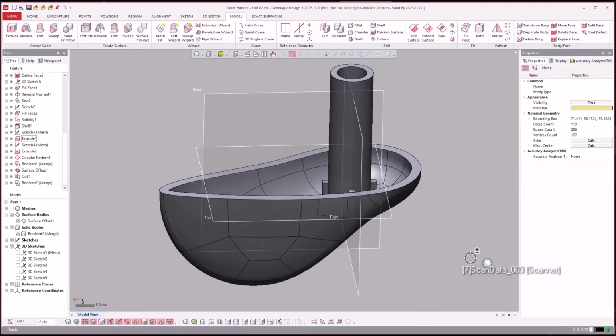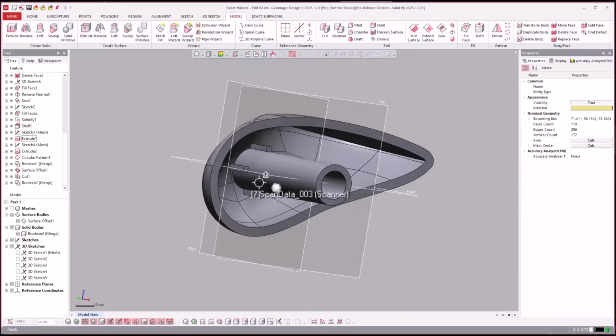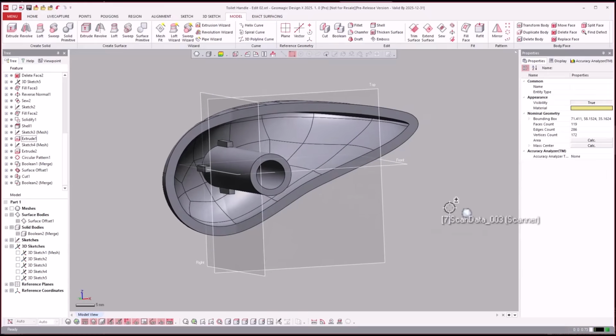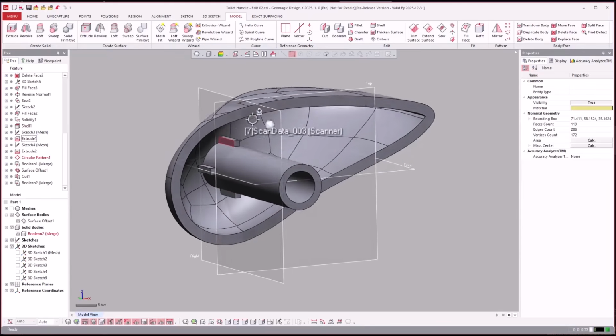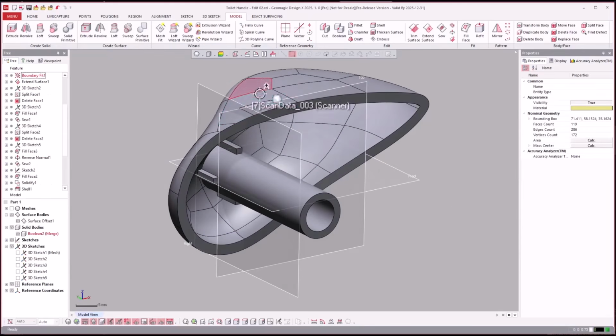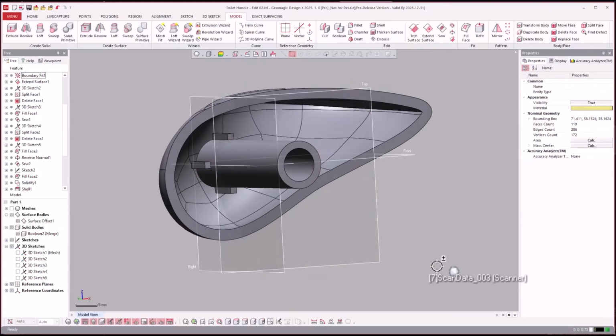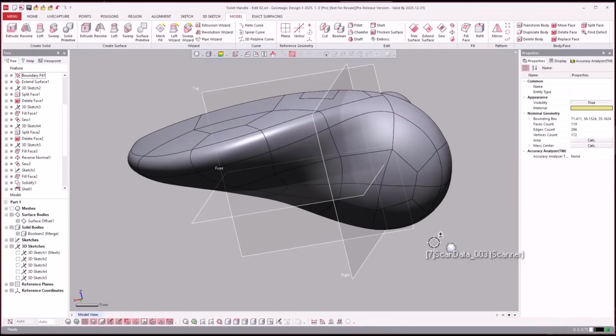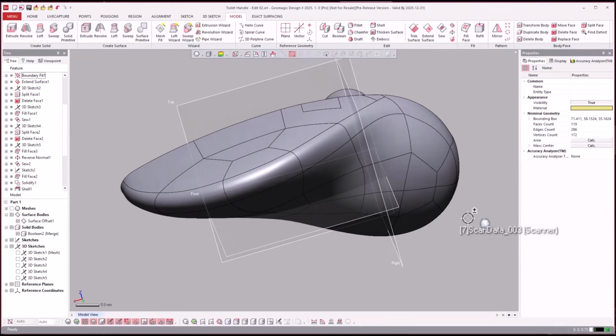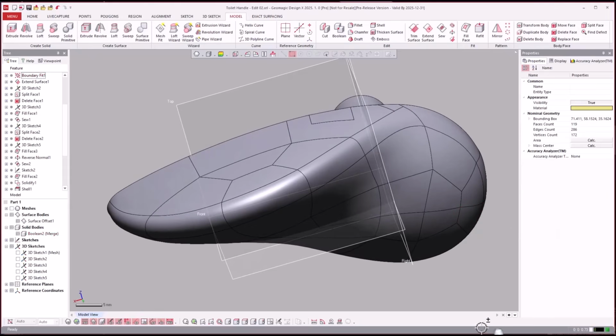So today, again, we focused on scan processes and creating a script to merge them together. Reinforce the alignment techniques of how to align a part when sometimes it's not readily apparent how to align a part like this. And then spending extra time going through some techniques that were used, the boundary fit surfacing and solidify. Don't forget about that tool in here because it's very powerful to create solids. So with that, let's go ahead and jump back over to the PowerPoint.